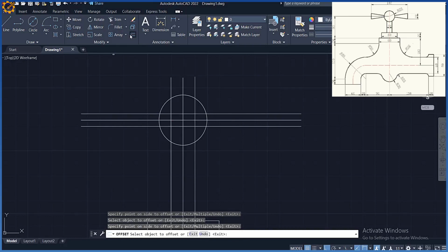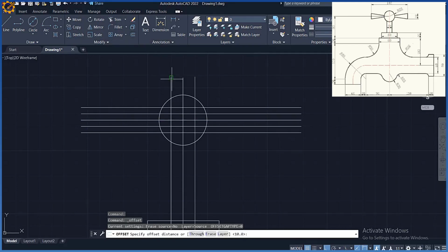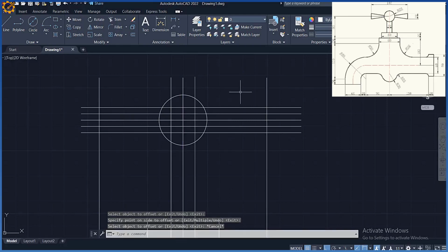So then I'm going to offset this also, mark of 10, enter, from this midpoint to the top and to the bottom right there. Okay, so then I'm going to offset this center line, 140, mark of 70, enter, 70 to the left and 70 to the right. Okay, so after doing that, let me pick my trim first of all. I'm trimming the whole of this out.